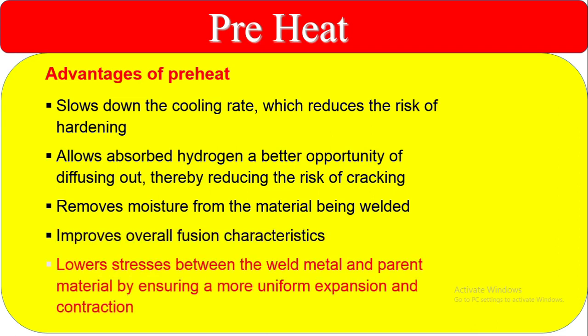Fifth, it lowers stresses between the weld metal and parent material by ensuring a more uniform expansion and contraction. So when preheat is applied, lower stresses will be generated. So you understand the advantages of preheat, and also you understand all the requirements of the heat treatment.